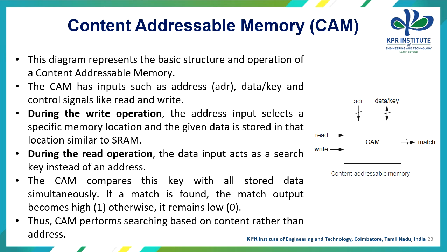During the read operation, the data input acts as a search key instead of an address. The CAM compares this key with all the stored data simultaneously. If a match is found, then the match output becomes high, 1, otherwise it remains low. Thus, the CAM performs searching based on content rather than address.